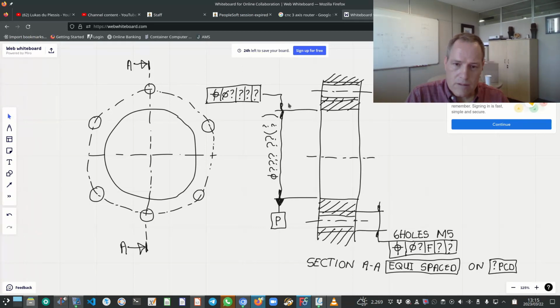You will also then, in line with this dimension line, add a leader line with a positional tolerance, diameters, whatever you decide it should be, and relative to datums, 3 datums. Okay, and those datums will obviously correspond to what you've specified in this view.